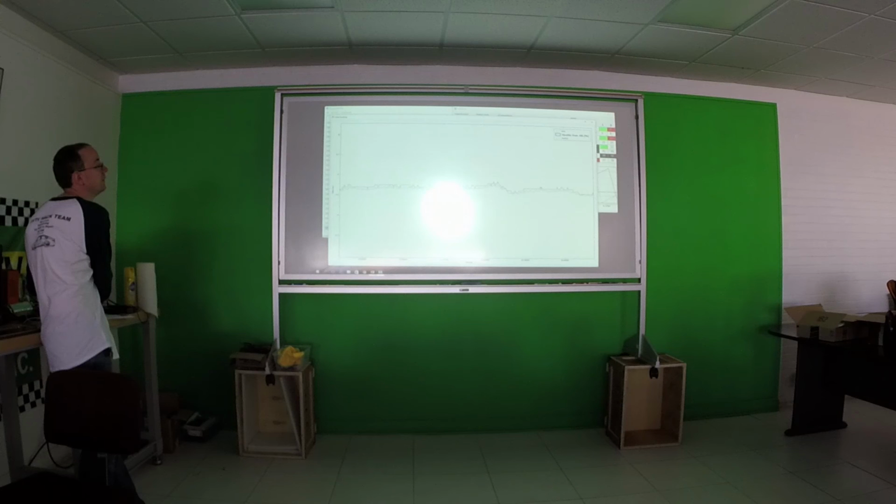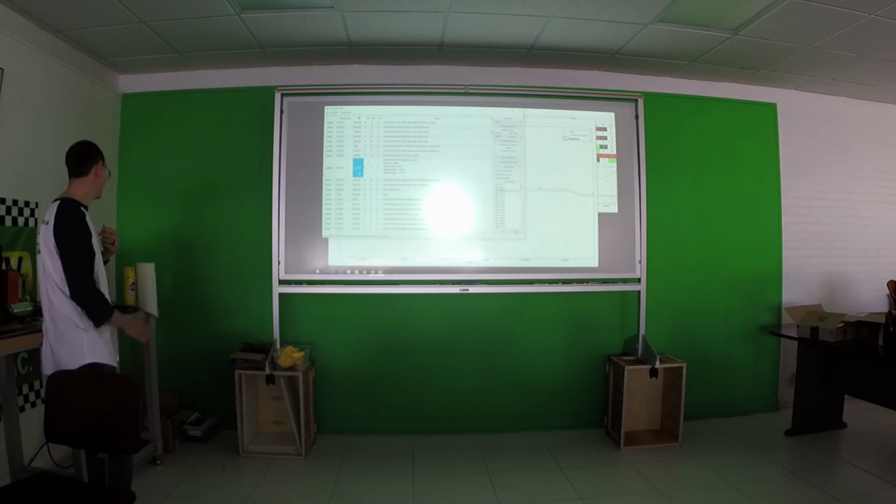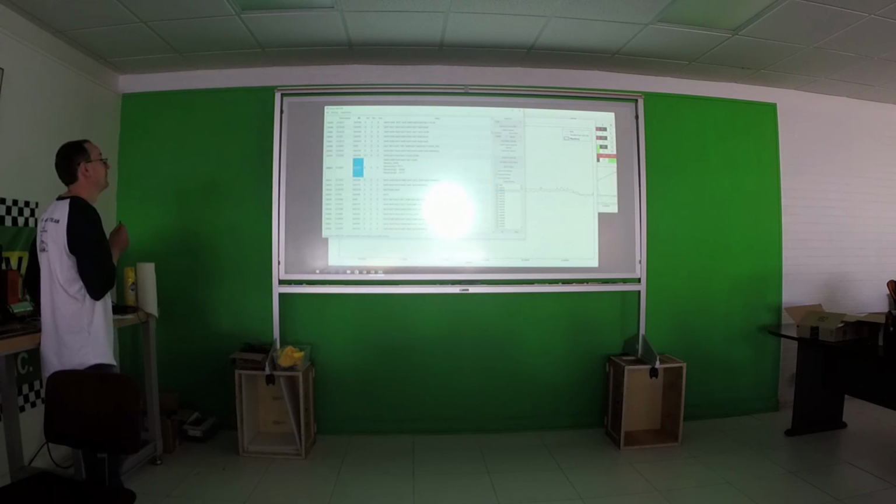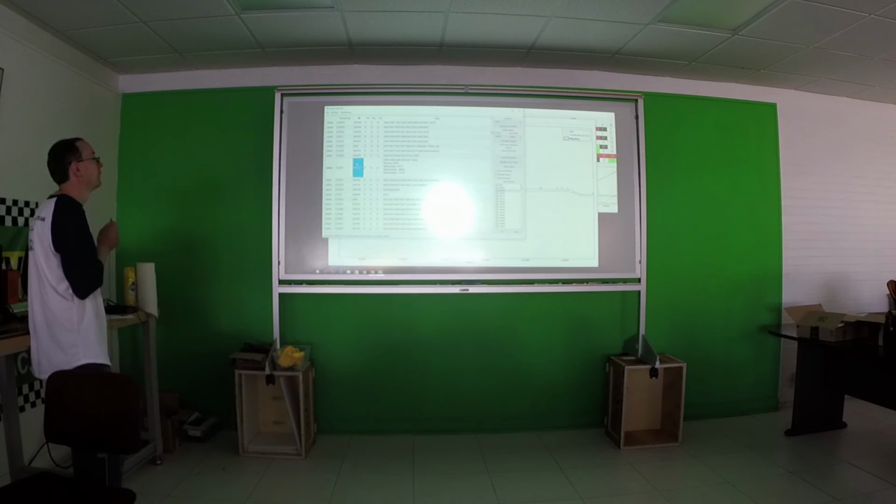You could, yeah, we could. You might be able to use that. You can click like that and come in here. That's 106, and the other signal is 102. So you could try to look in here. 102 is sent first. You might theorize then that because it's sent 5 milliseconds before, it's the actual master and this one copied the data. But it's still a guess. We sometimes have to guess, and we'll say 102 is probably that value, and try it and see if it responds. But there is a lot of trial and error in reverse engineering.